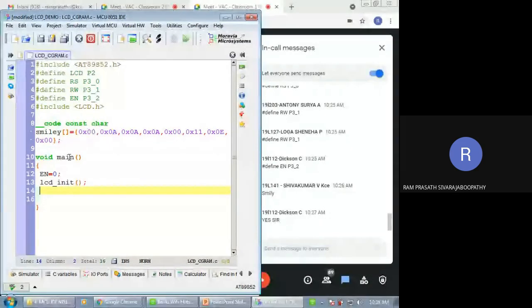Next, the LCD, whatever data we have written previously, it will get cleared. Third step, display turned on. Only the display we have turned on. Next step, entry mode set, that we have done. The fifth command we have given is set DDRAM address. That is the last command I have given, correct?